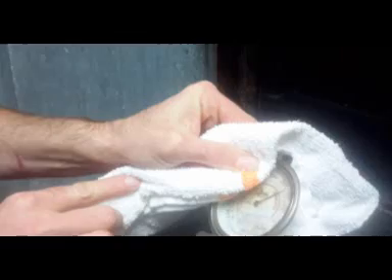As you can see, these are not convection ovens, so there's no air current to equalize the temperature. So on the right side here, we're getting about 370 is what we're getting there. And on the left side, we're reading about 395. That's a pretty significant difference for something that's heat activated.